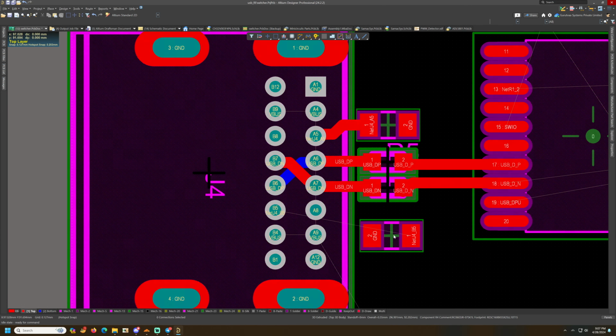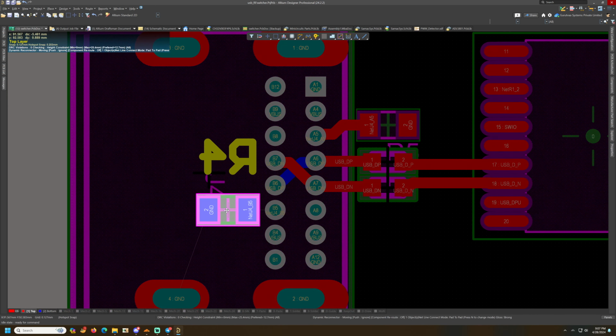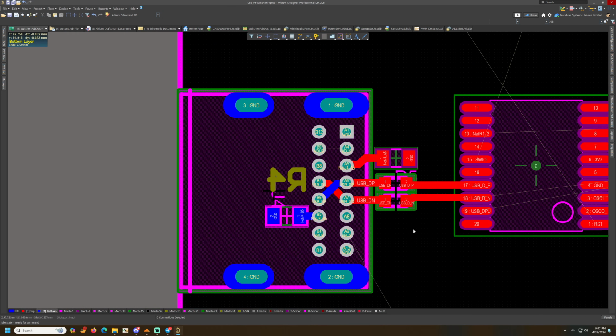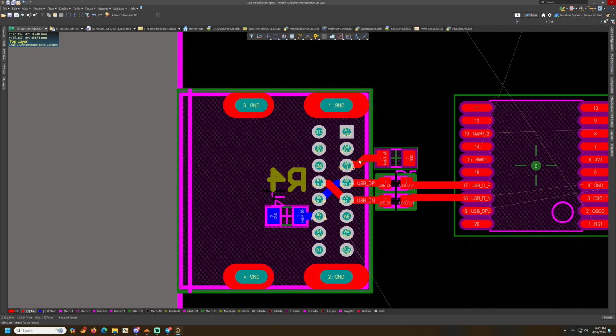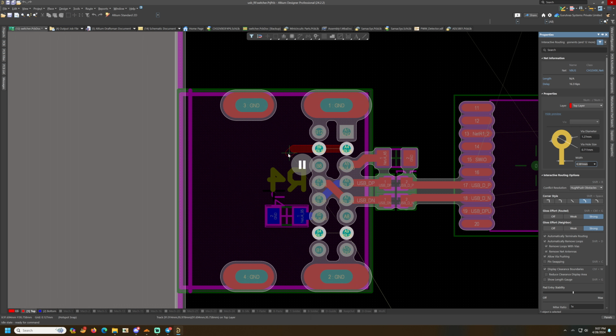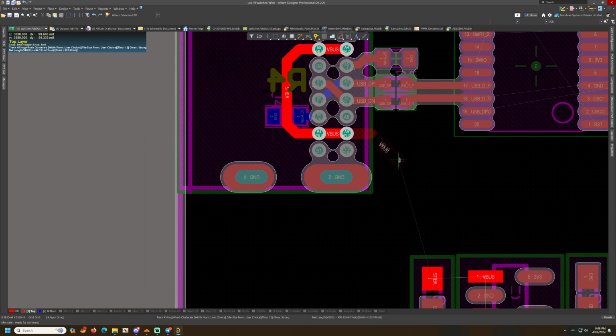The V bus pair powers up the entire board, so the V bus feeds the voltage regulator, which converts whatever input comes from the USB bus into 3.3 volts output, which is required by the microcontroller and the RF switch for its normal operation.